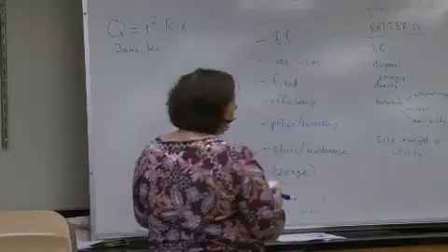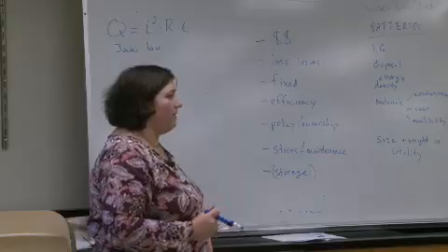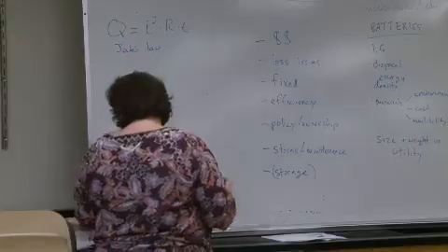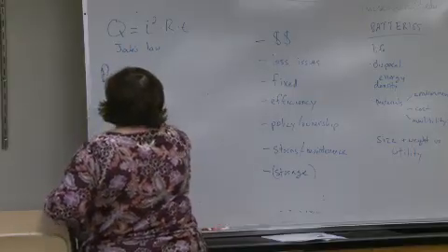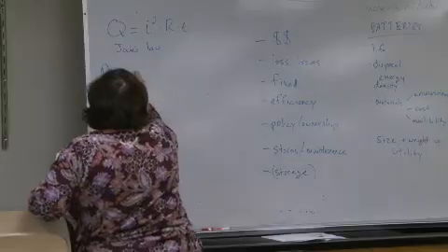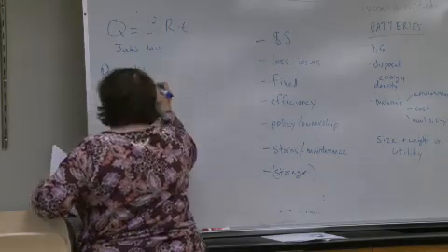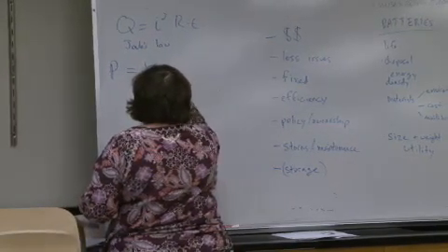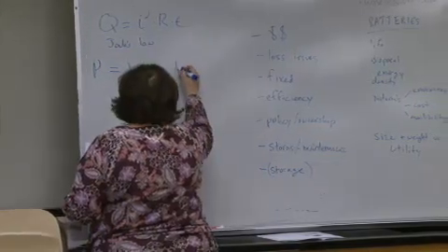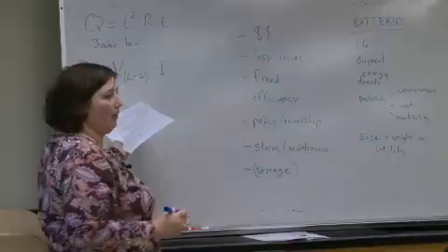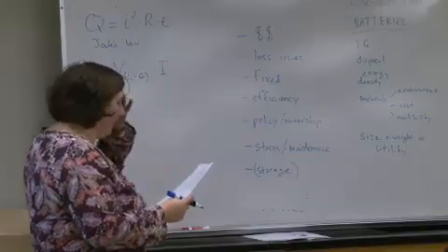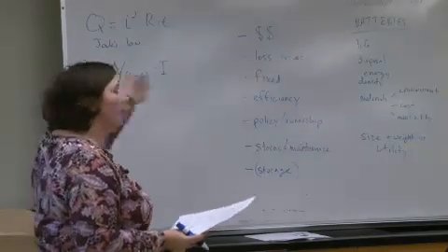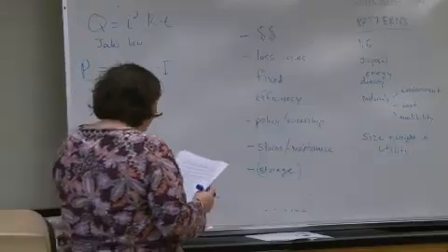So let's pretend that we're trying to deliver power from some power plant in Western Mass to Boston. We're going to call the power that we need power with a capital P. And power, as we recall, is the voltage, from the line to ground, times the current through the power line. So P equals VI, but we also have the issue of the power loss that we know is happening through the wire. To calculate that, you're using the same equation.